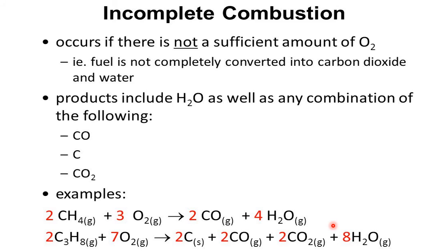All these conditions are there which we don't follow. In the beginning, when the engine starts, we first have to keep the engine on for about five minutes, so that the engine gets ready for the journey. Then slowly you have to increase the speed. But nowadays we don't have time, so we hurry. Suddenly we use the accelerator, thereby giving less time for combustion of the petrol or diesel, whichever fuel you are using. That gives out unburned carbon particles or carbon monoxide if it is severe incomplete combustion.